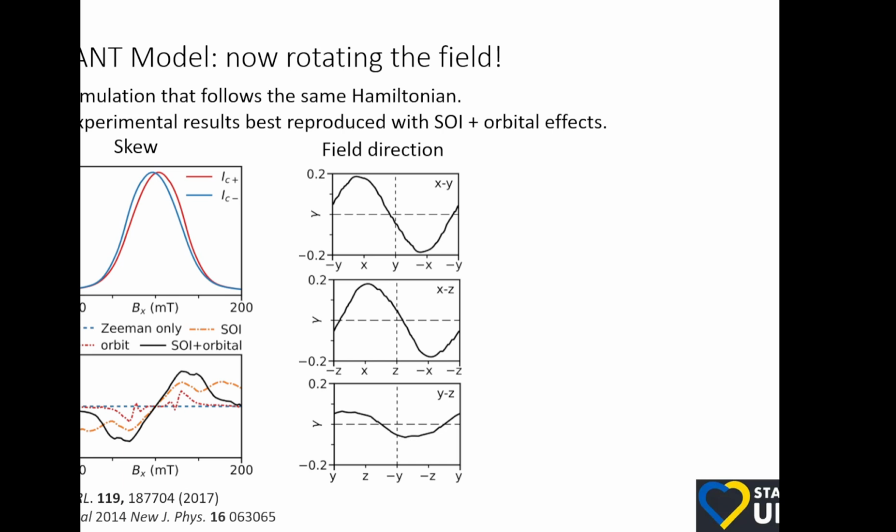These kind of patterns are actually very easy to imagine. For instance, suppose you have a junction and the current is flowing along the junction. There is the Biot-Savart law, which tells you that there is a magnetic field generated by the current. If the current is large enough, the magnetic field generated by the current can put flux into the junction and cause some interference.